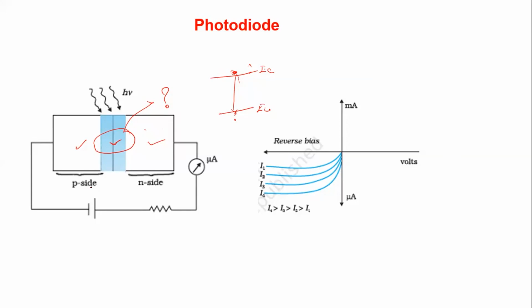In the photodiode, there will be a reverse bias, right? This is to increase the depletion region, so that we can increase the efficiency of absorption. In the opposite sense, we have to reduce the recombination process. Clear? So we know that once the carriers have been generated, then in reverse bias the current will be flowing. We will get the current in the reverse bias.